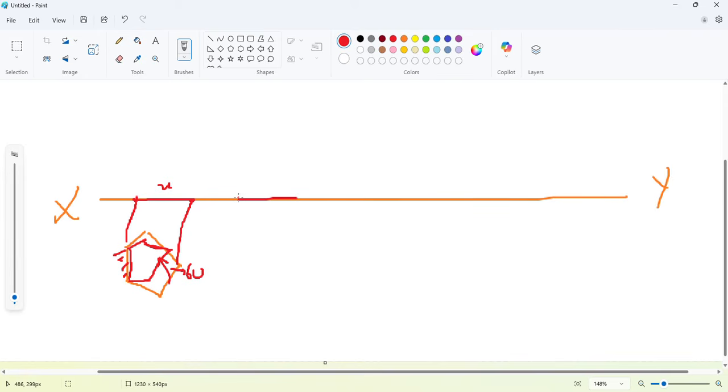Now after rotation, when the plane is resting on one of its edges and makes an angle of 60°, in front view we will get an inclined line, because while resting on HP we are getting a straight line on the front view which is on the reference line. But when the surface gets rotated by 60° with the HP, then in front view we will get an inclined line at 60°.